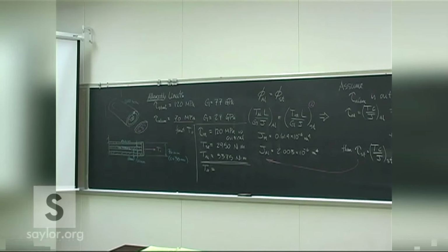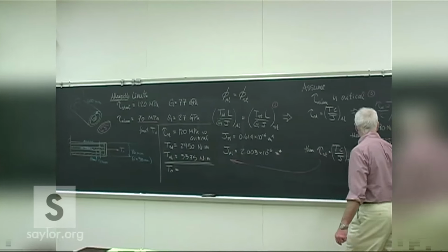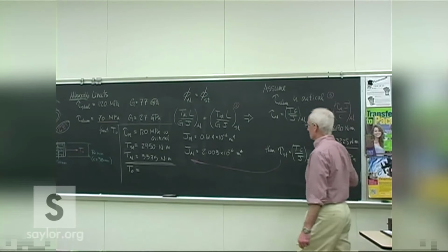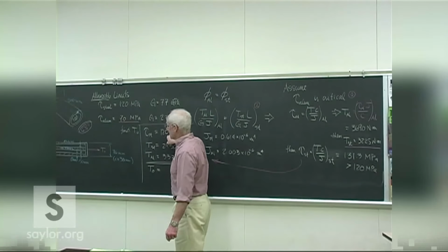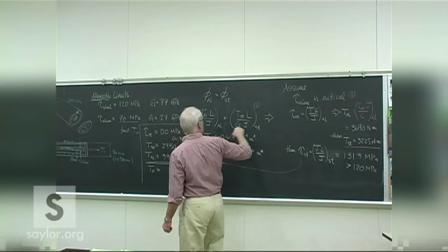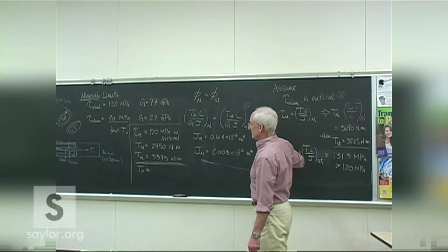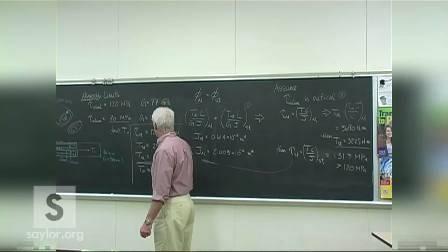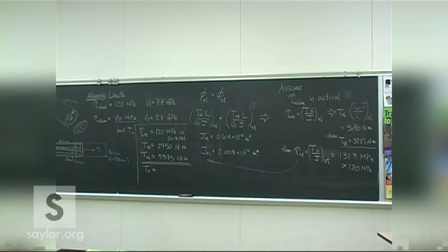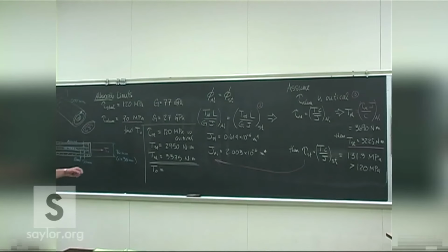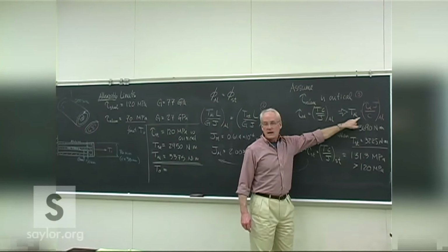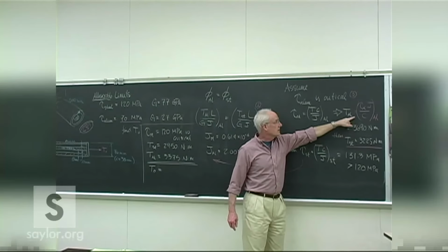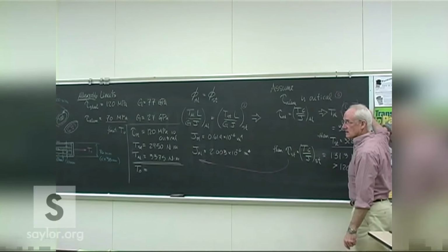So we go back to this. You're right here, know that that's over the limit for the steel. So now we go back and assume this value, the limit value, for the steel, and essentially redo the calculation, only each of the different pieces swap the roles. So now that we know that the steel is the limit, calculate the load in the steel using this same equation only for the steel.